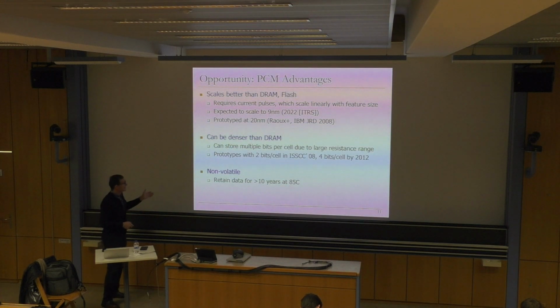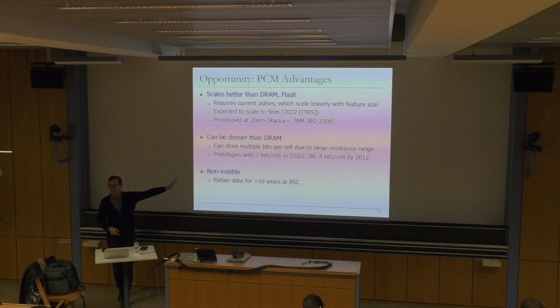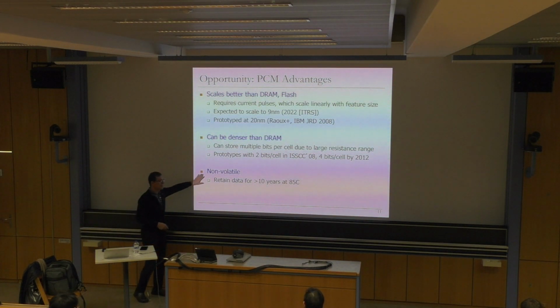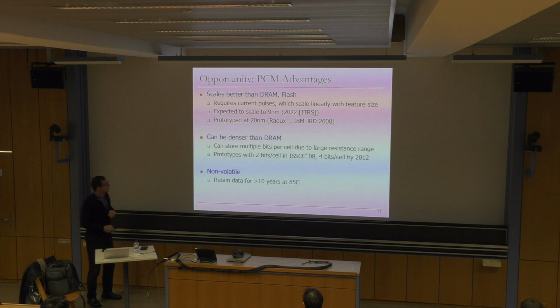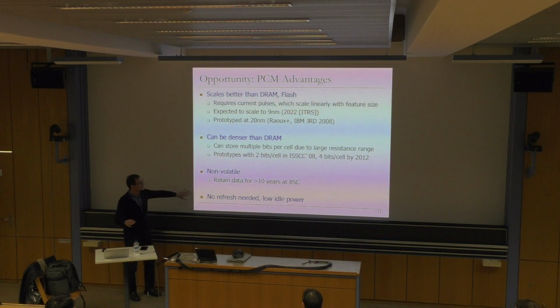It's non-volatile. It can retain data for clearly much longer than DRAM, right? Although there are issues related to this also. You may need to refresh this also. We will talk about that very briefly. There's no refresh needed, ideally, and it leads to low idle power because your leakage is very low.